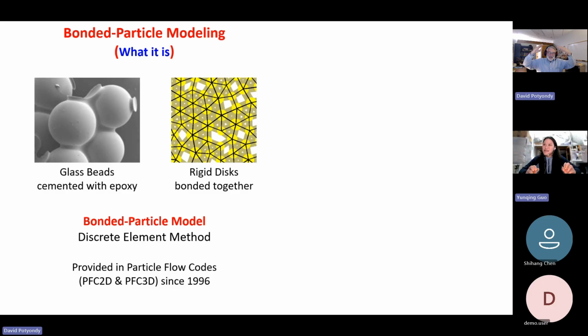Now when material collapses, it bulks. They call it bulking. So what would happen is it breaks apart and it collapses, but then it fills up all the space, and now it's self-supporting. So it doesn't collapse all the way up to the surface. It only collapses maybe 20 or 30 meters above where it started. It's a big pile of broken material.